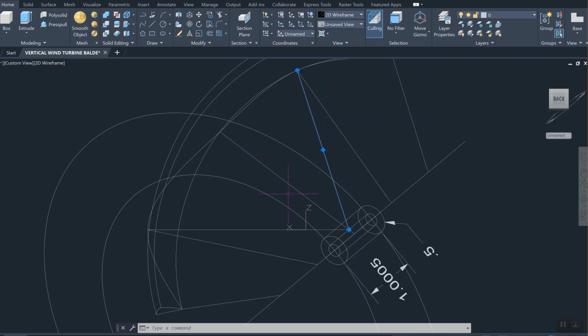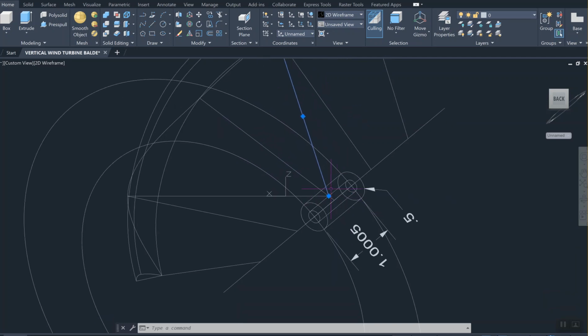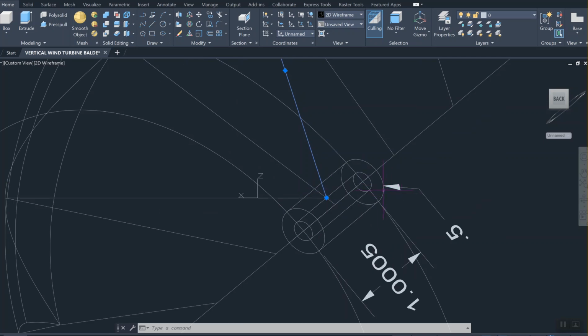But the supports are supposed to join to the center hub. That hub is actually 0.5 inches diameter and 0.2 inches diameter. Two circles are extruded only 1 inch, okay? And I did this without a video description of it because this is a very simple hub. I literally extruded these two circles and it created two solids inside each other, and I used the subtract command to subtract the first solid from the second solid, so that you can have a pipe here.